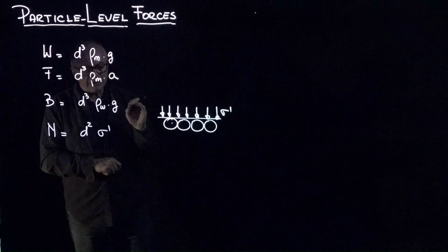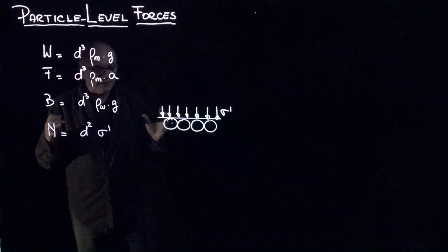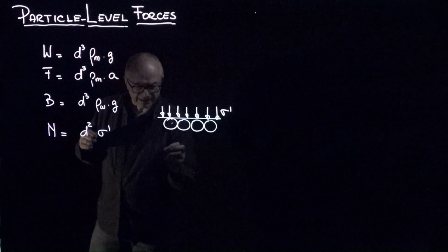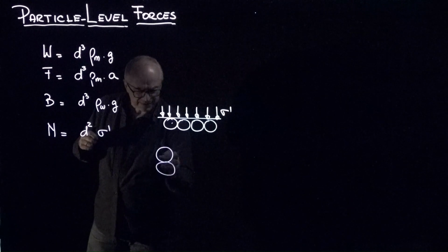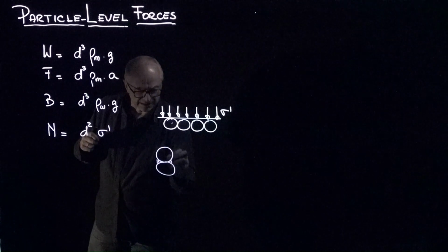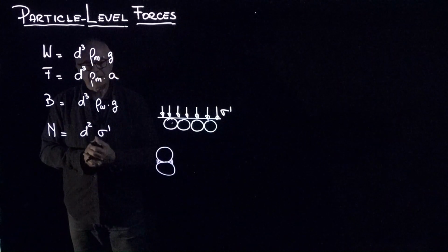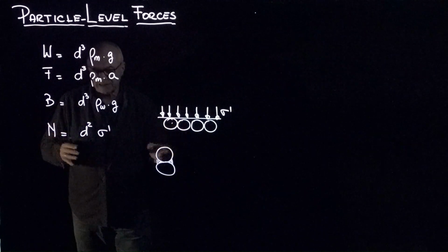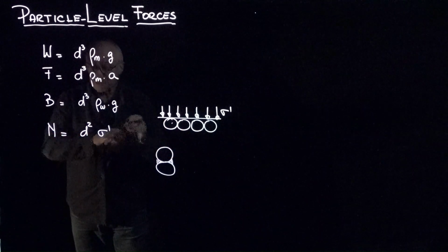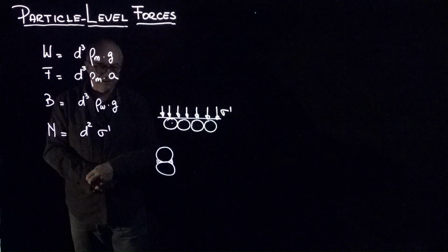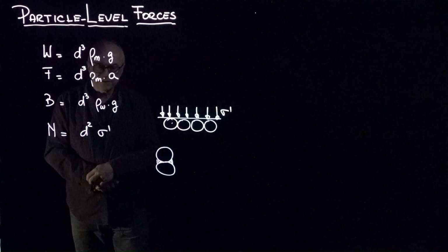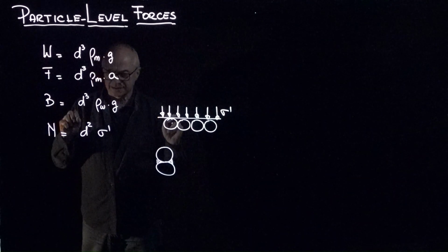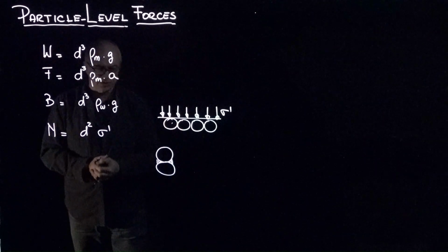Particles in a soil mass often experience some form of diagenesis and cementation. So, for example, a particle could have some sediment precipitation at the contact, and that can have a tremendous implication on the stiffness and the strength and the dilatancy and the hydraulic conductivity of this material, with very early and minor cementation that most often goes undetected, but we should actually pay close attention to it.